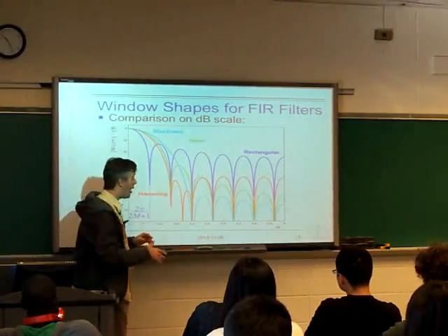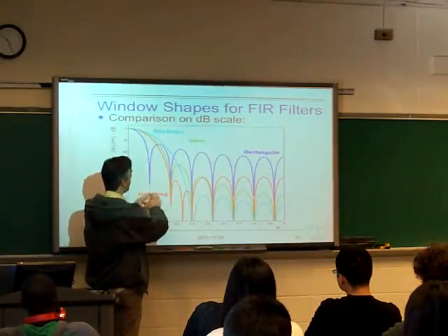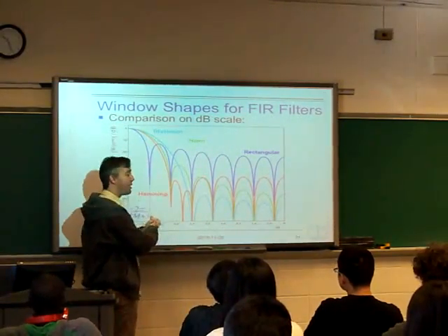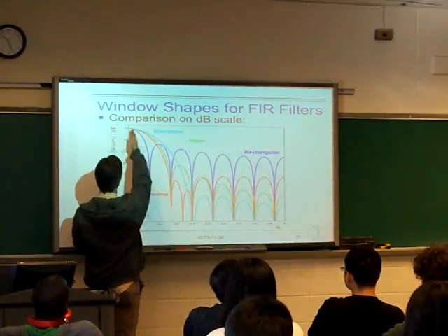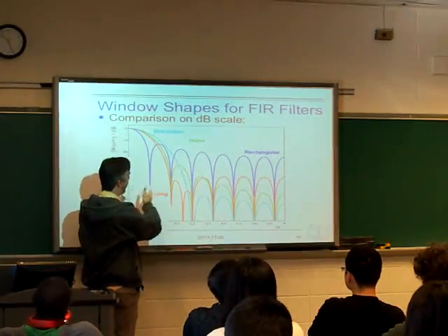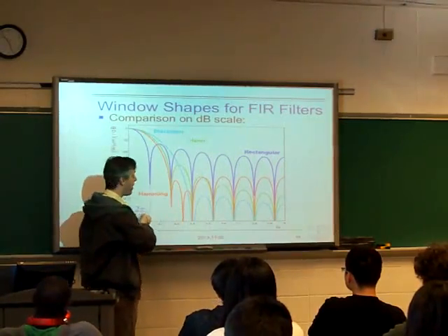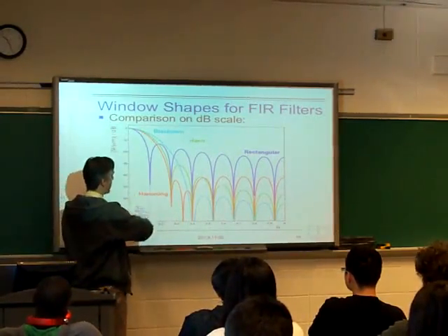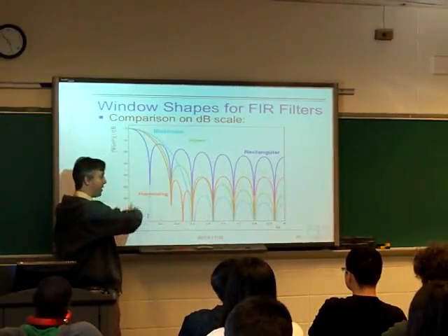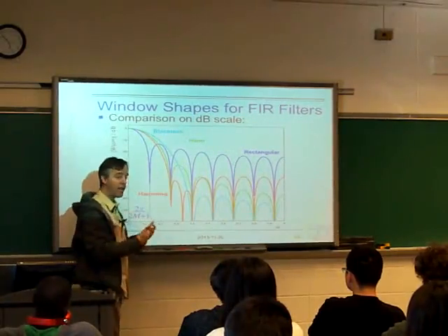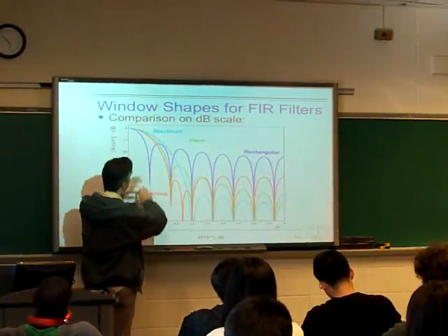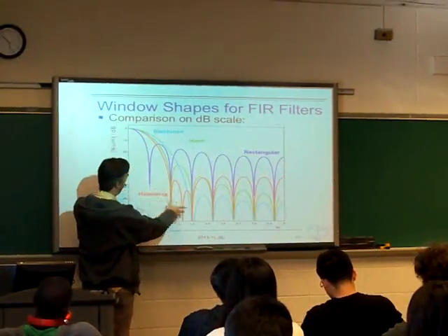And so just to remember, this would be the frequency response if we tried to build a band pass filter for a single frequency, or a low pass filter that only passed DC, only passed zero frequency. This would be the response, because that would be convolving this with an ideal response that was just a delta function. In general, we're convolving this with some other ideal response, which is maybe rectangular, and so we're going to blur this with some rectangular functions.